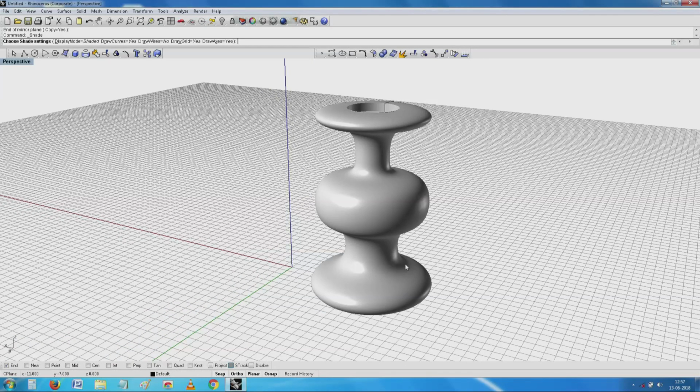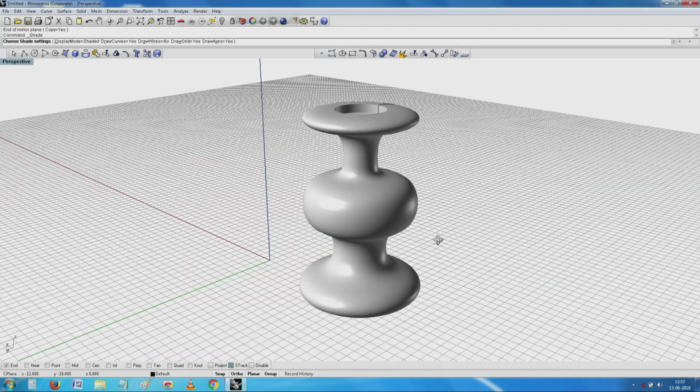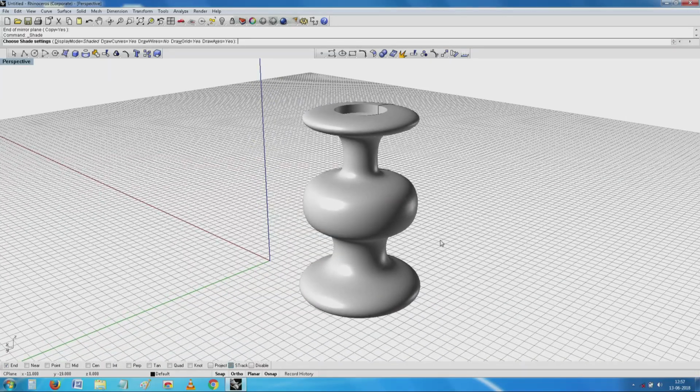One of them is that these profiles are determined by the voltages and the corona and the arcing that can take place. When you have this corona and arcing, these radiuses become very critical. Though I have randomly written this, and it does have an interesting look, in reality a lot of thought goes into it.